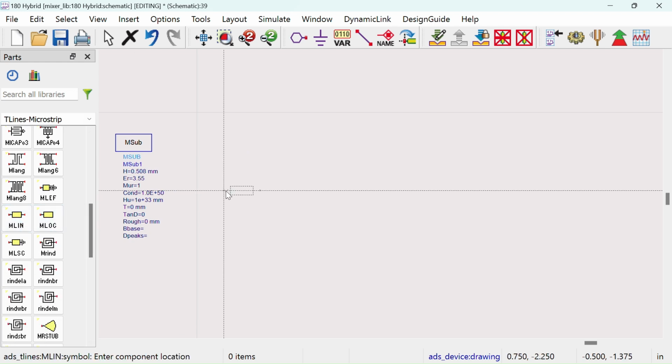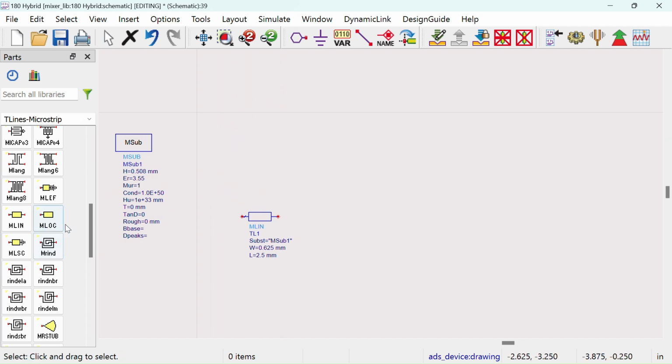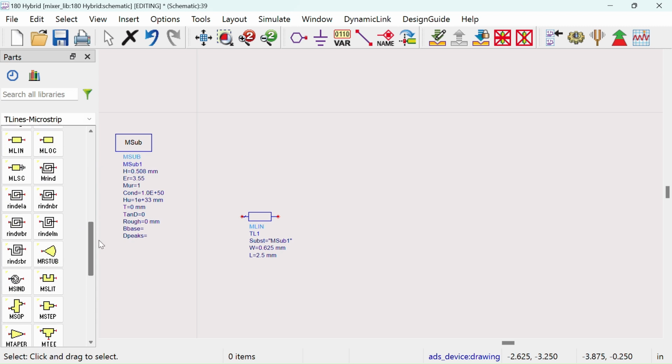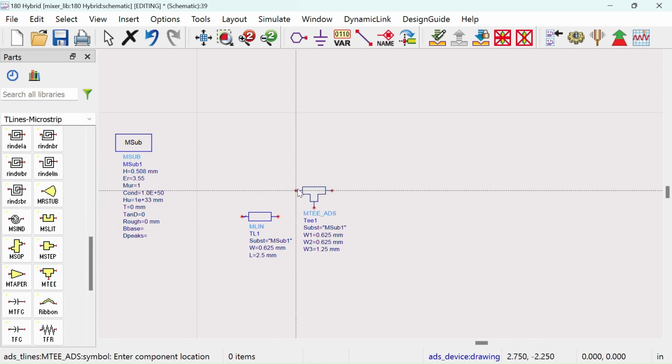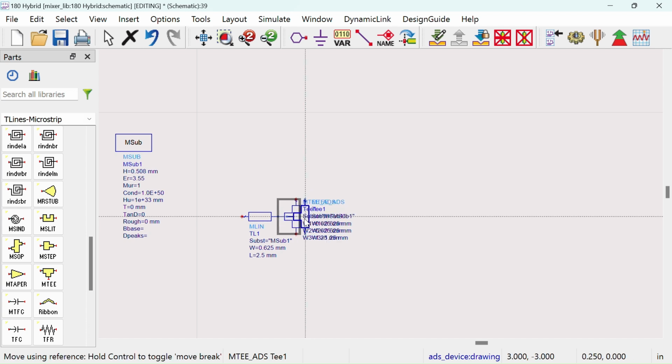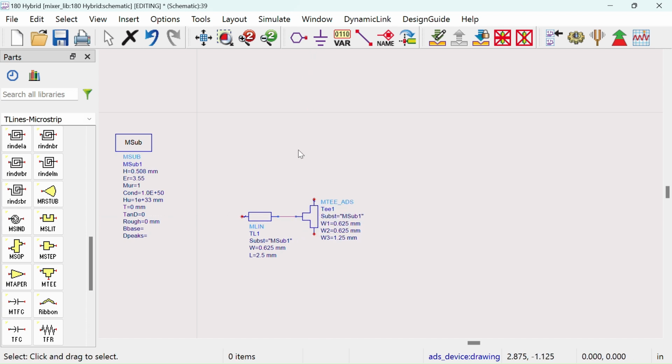And bring the microstrip lines. Using the curve lines, we would be able to create the phase shift between different ports. The distance between each port should be lambda over 4, to have 2 ports that have the same amplitude but 180 degrees phase difference.